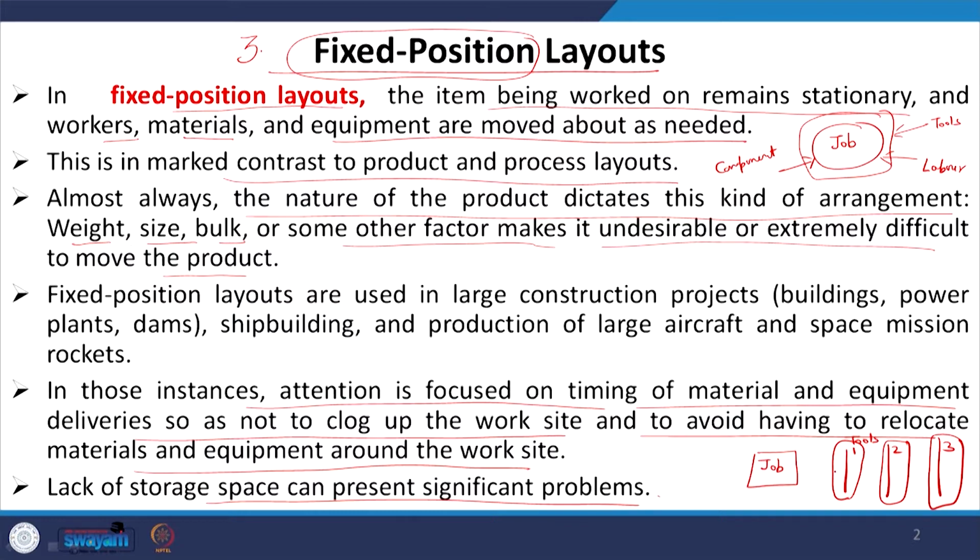We should place our tools with respect to the job in such a manner that those which are frequently used are placed closer, and those which are not so frequently used can be placed at a distant location, so that you can minimize their movement. If you place frequently used tools at a distant place, it will lead to larger movement. So that principle of minimization of distance movement is applicable even in fixed position layout.